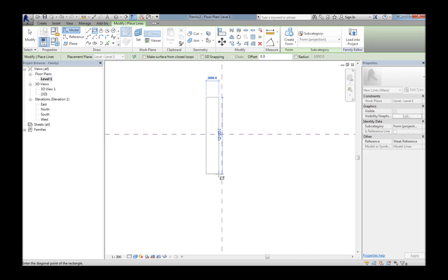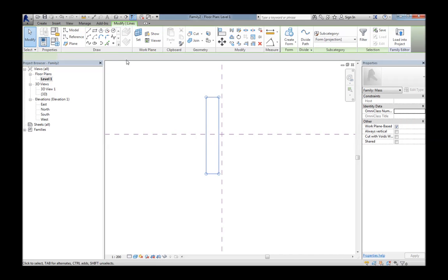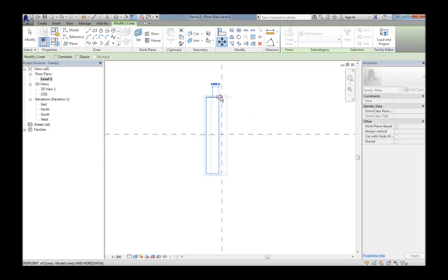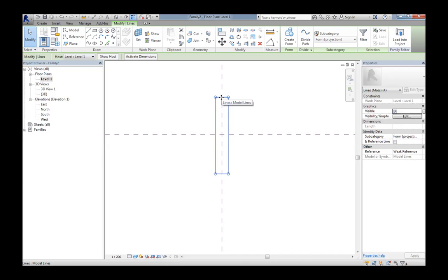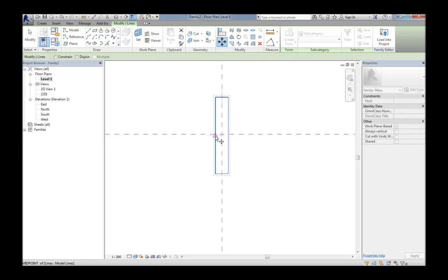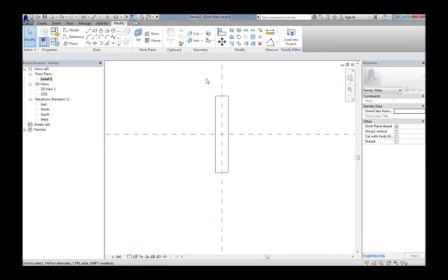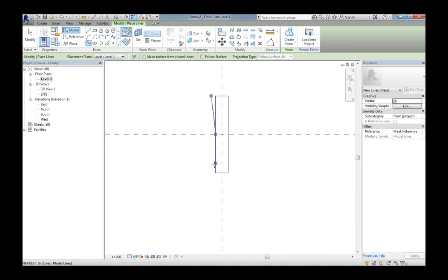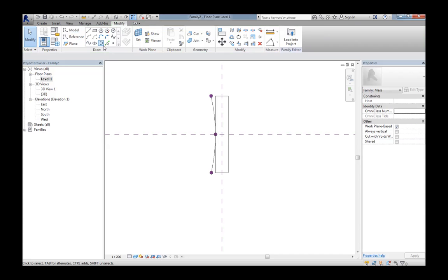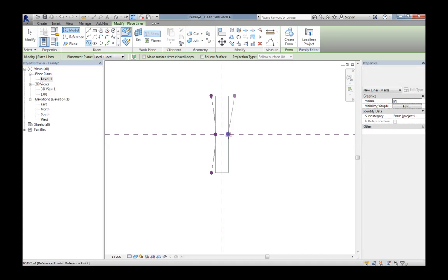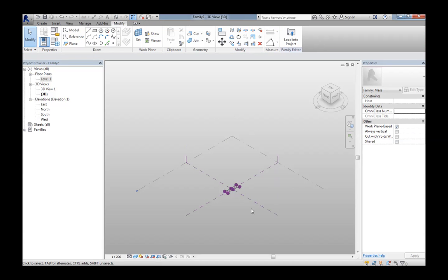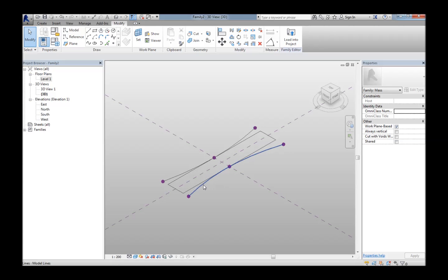We're going to draw the extents of the bridge, the Floral Street Bridge example, and the overall extents. And then after that we're going to draw splines, two splines that will be the rails that will hang the adaptive family onto. So there's the first spline, second spline, and those are the two curves that will control the placement of the adaptive family.